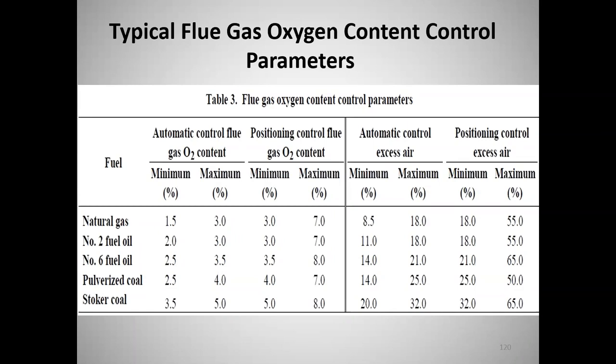That's not nearly as good as sensing your air or oxygen levels directly and controlling the fan off a measurement. It's just a mechanical linkage to the fuel valve.